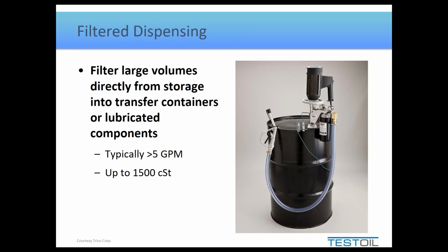If you buy these filter manifolds and install them on the output of your barrel pumps, I encourage you to buy twice as many filters as you require. An automotive filter is not a great filter, but one pass of filtration is better than no passes. The reason I say buy twice as many filters as you need is that if you take the extra filters and thread a little 2 or 3 inch nipple into the bottom of the filter, you turn it upside down, it'll thread right into the small bung hole on that drum, and it becomes your breather, and a very inexpensive breather at that.